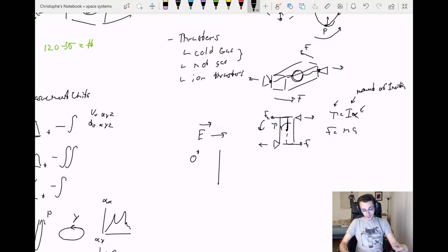But the problem is they are accelerating these really small particles at really fast speeds, so they don't give your spacecraft a lot of momentum, which means they don't give a lot of maximum thrust. So oftentimes you'll see ion thrusters used over very lengthy periods of time. Instead of giving like 40 million newtons all in the space of a minute, you're going to use like 1 or 2 newtons over the period of months or years, which is helpful in deep space, where you have that amount of time to shift your orbit ever so slightly in some directions over long periods of time.